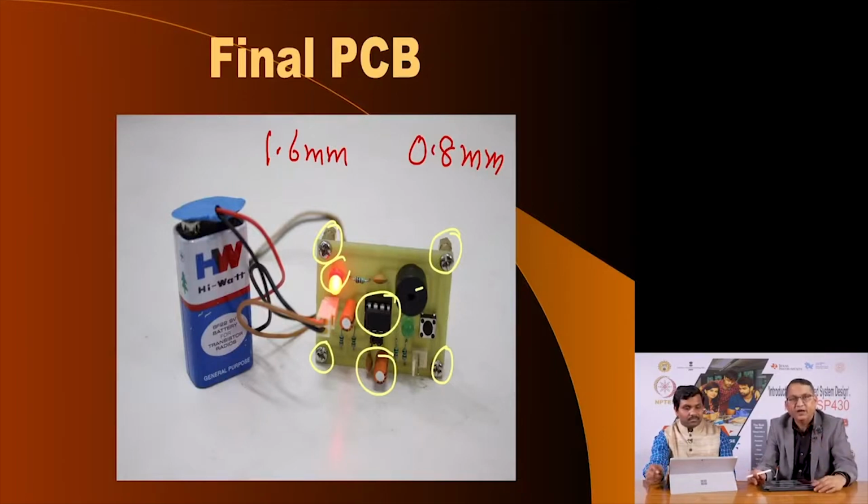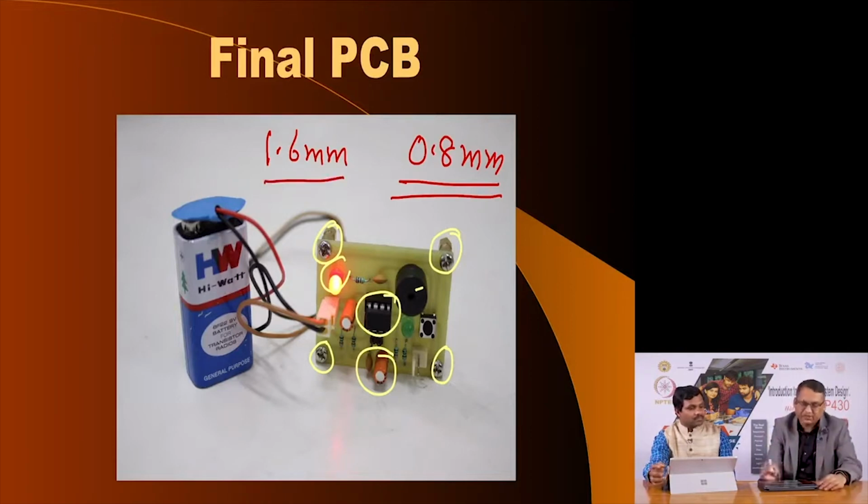And when you want to make a double sided board, we choose to use 0.8 mm thick PCBs. Each PCB will make one side of the layout, and then we align them and glue them together and put wires through holes, so that the two PCBs join up and make like a 1.6 mm PCB. So, it is possible to prototype a double sided layout also in the lab.